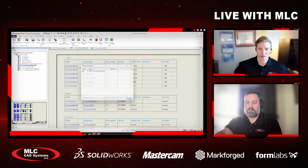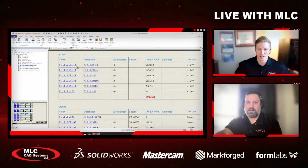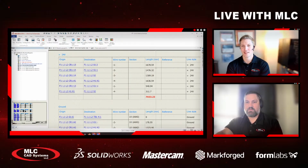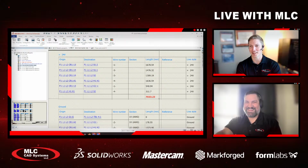And when I do that, you'll now see a total length for each style. Okay. So now we have a cut length. So not only do we have a length from CR1 to S1 at 1600 millimeters, so just over 1.5 meters, we now can total up the total length of that style. Yeah, so we only need to buy 7 meters and 33.23 millimeters of wire exactly.